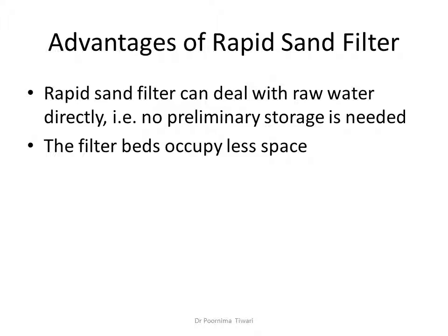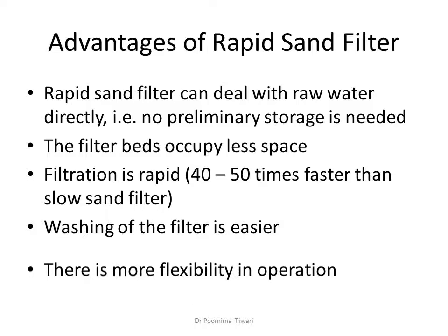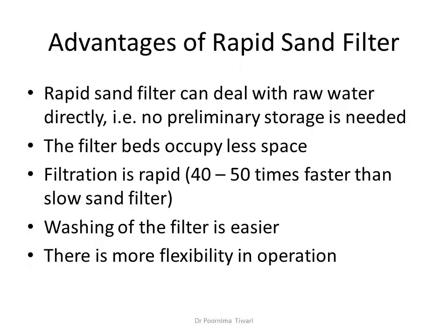These filter beds occupy less space and filtration is rapid, 40 to 50 times faster filtration than slow sand filters. The washing of the filter is easier and therefore there is more flexibility in operation. The disadvantages can be simply guessed: the operation requires qualified operators, frequent washing is required, and the water quality is a little inferior to that produced by slow sand filter.